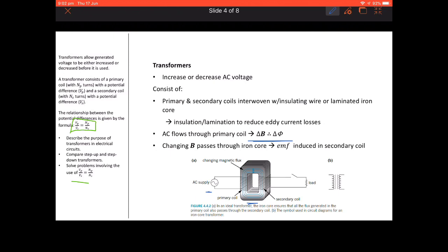If you've got an electric current, there'll be a magnetic field that surrounds that current. If you've got a conductor that doesn't have any current flowing in it, but you bring a changing magnetic field along and expose that wire to it, then that changing magnetic field will induce an EMF, a voltage, and it therefore will induce a current in that conductor. So they can induce each other. An EMF will be induced in the secondary coil, and that EMF is dependent on the number of turns in that coil as well as the number of turns in the primary coil.